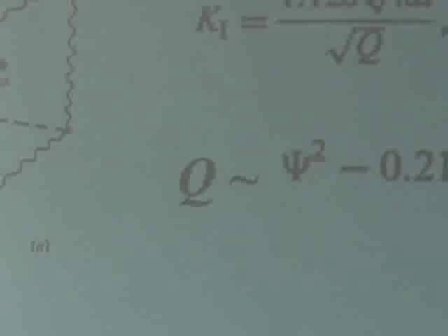It's mostly an effect of being really in a plane stress condition. So the sheet can become thinner in the thickness direction, close to the crack where we have all those high stresses that we talked about. So when that happens, you get a lot of deformation. And deformation means it's not separating at the crack tip. It keeps blunting more and more as you go. So that's really what happens.